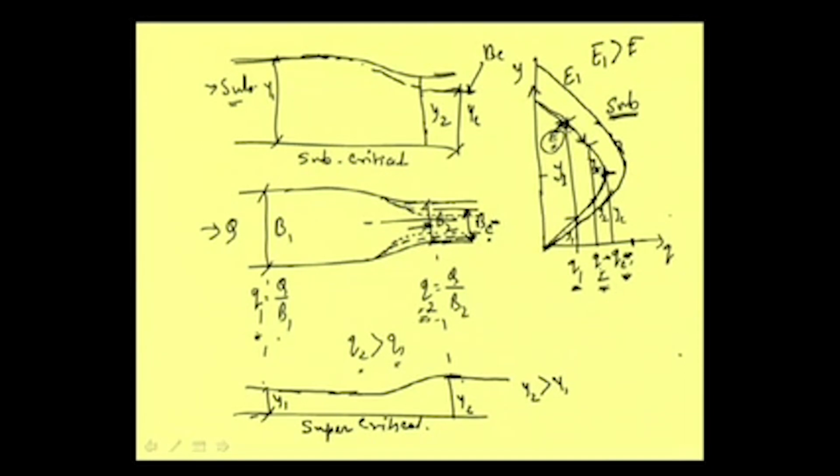And at this higher energy level, what will happen, and to what extent will it rise? Because it is rising just to push the water through this point, and it can push the water when the depth at this narrow portion is again critical, that is, the maximum discharge possible here is critical at the critical section.